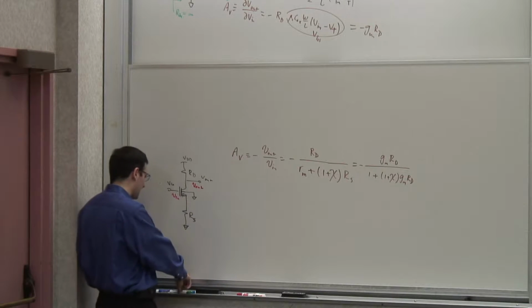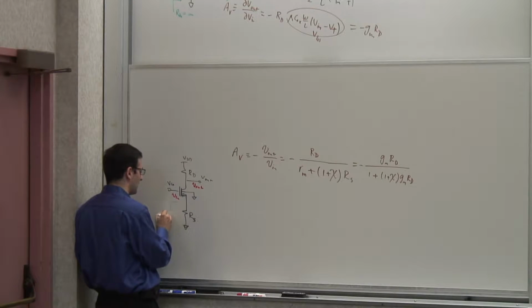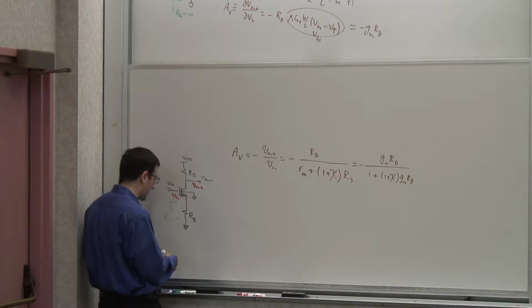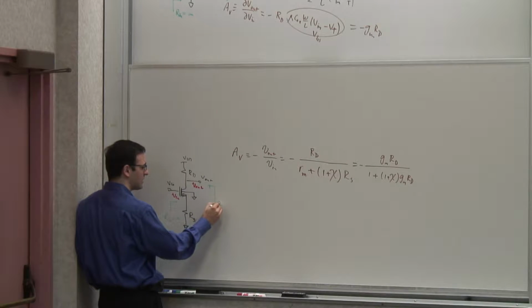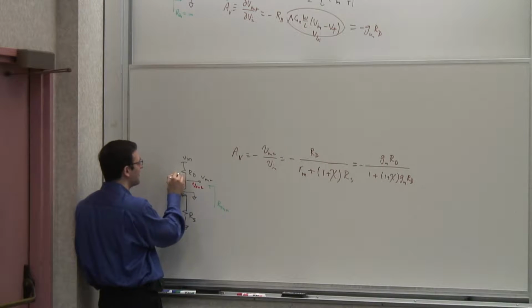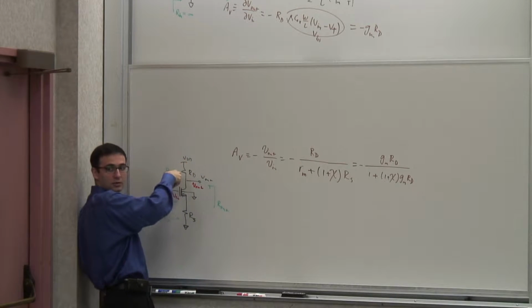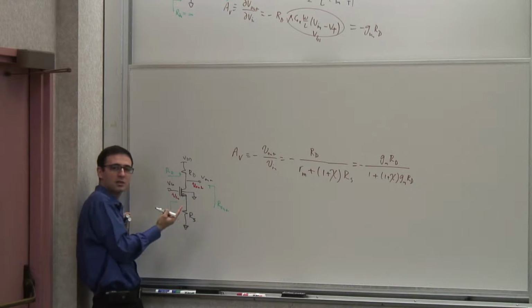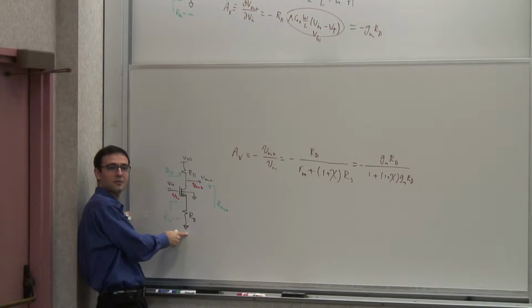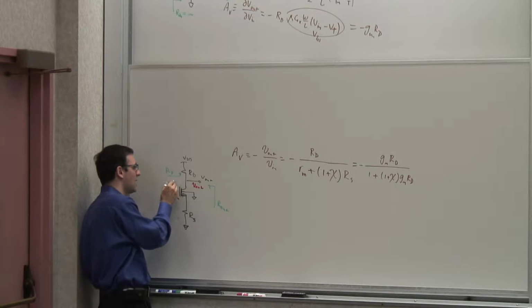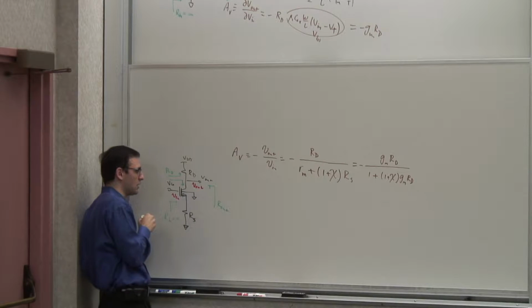The input resistance again is simply, based on our model, very large at low frequencies. And the output resistance, again, consists of two parts, the intrinsic and extrinsic parts. The extrinsic part is simply RD. It's whatever you put in there. So whatever you see looking down into this thing is going to be in parallel with that from a small signal perspective, because this node is ground and that node is ground too from a small signal, variational perspective. Now, the question is, what is this that you see looking down here?